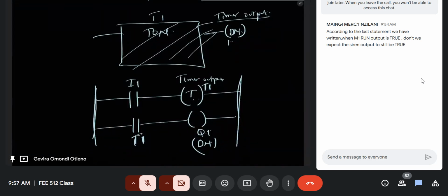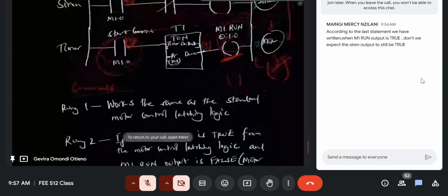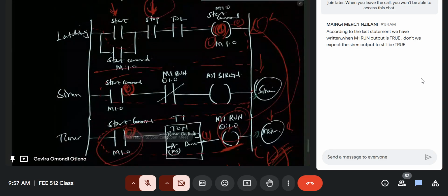Okay, if I hear you correctly, you're asking about the sequential ordering that I told you about. That is for us designers to understand, but the key thing is the scan cycle. The scan cycle is what determines how you design your ladder diagram, because you have to think about how the processor will run through and understand each rung.